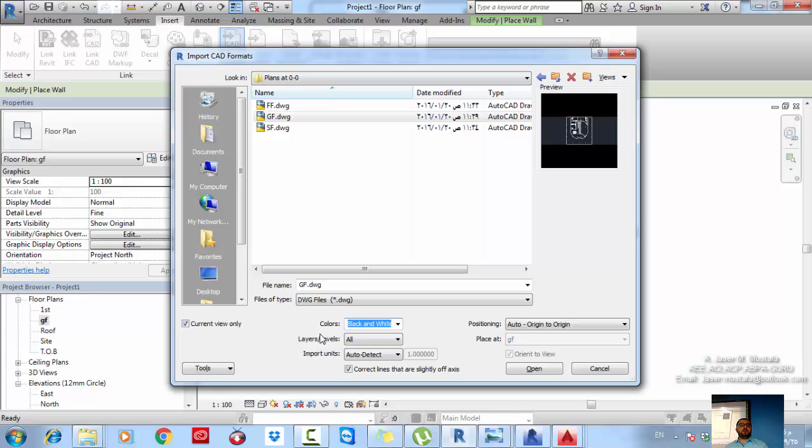What are the layers that you are including? If you have visible and hidden layers, just click on visible layers. Okay? If you want all the AutoCAD layers, you have the option, and if you want to choose out of your layers, also you have the option. I usually keep it as all layers. Why? Because I am working on the files, so I know what are my layers and I'm not using too many layers. Okay? And usually when it's a small file, you don't care for this option because it's not that much load on your computer.